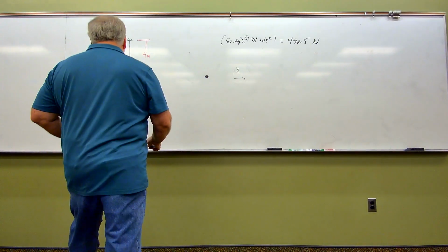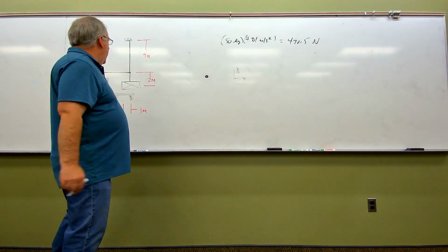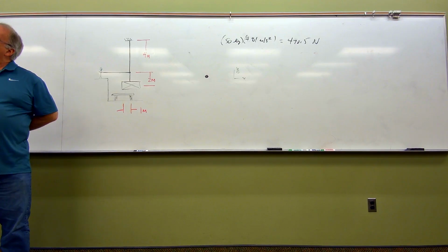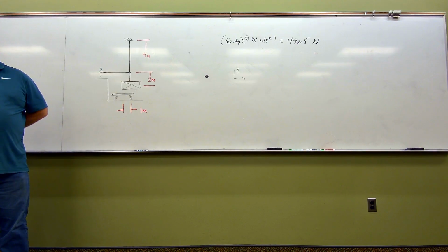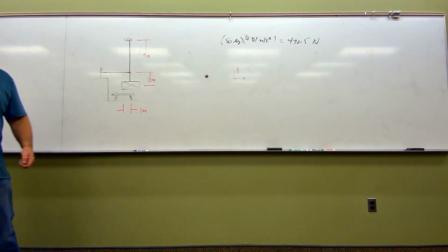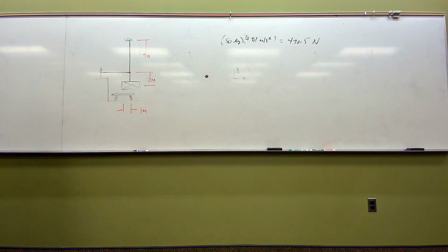And now, coming off of that, a free body diagram means I've drawn a representation of the thing that I'm doing the free body diagram of. Now I'm going to include its weight. We know nothing about the weight of the rope or the weight of the knot, so I'm not worried about that. And then we just go around the horn and say, we've got forces wherever I used to be connected to something, wherever I used to be in contact with something.